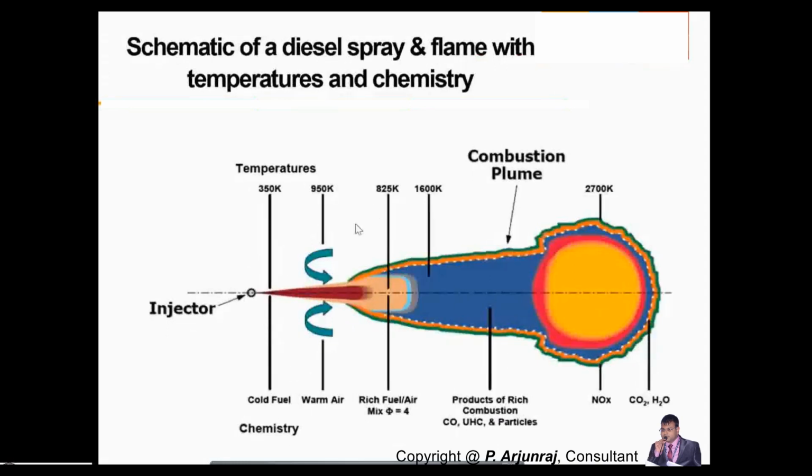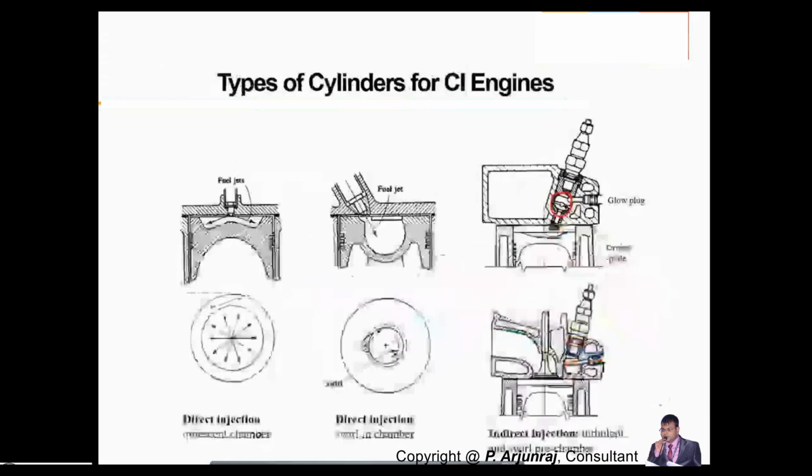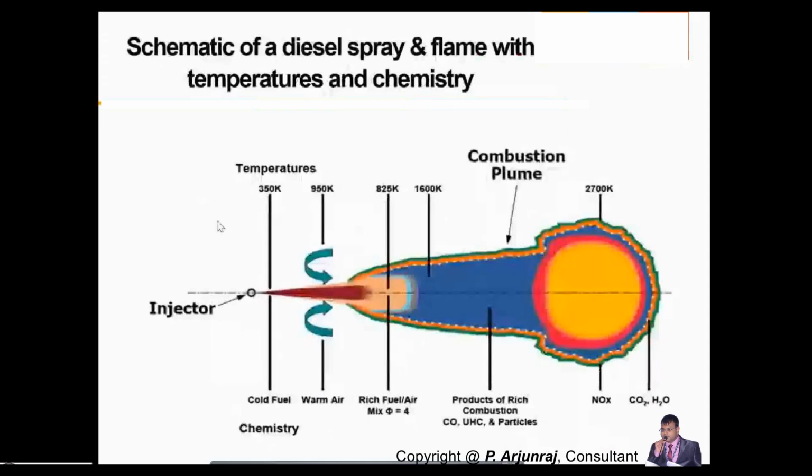Sometimes the temperature may not reach the expected level, but this is still quite a good method to reduce NOx as well. When you are reducing the temperature with the help of the pre-combustion chamber, the overall temperature you get is going to be lesser. You reduce the peak temperature, so your nitrogen oxide emission is going to be lesser.